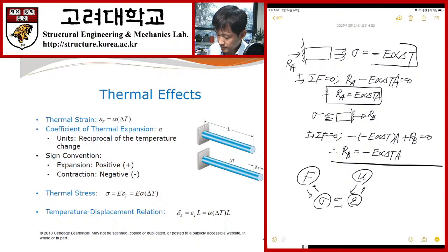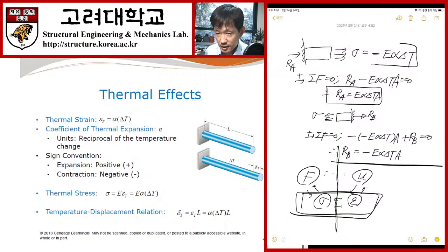So in this diagram, if you draw a line here, the force stuff have nothing to do with displacement, okay? So unless you consider the stress and strain relation, the force stuff is governed by the nonlinearity found in stress axis. That's why actual superposition of stress field is not that straightforward, especially if you have nonlinearity.